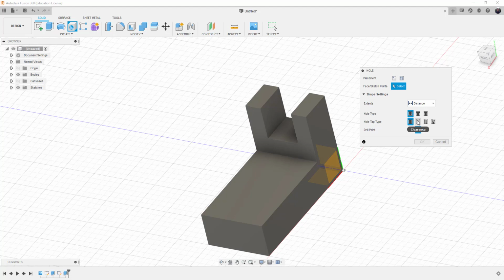We're not going to tap the hole, meaning we're not going to provide a clearance hole so it's slightly larger than the actual hole size, or tap it with threads, or taper tap it with like a pipe thread, which is tapered, an NPT thread, which is a tapered thread. So you get a watertight, airtight seal with that taper.